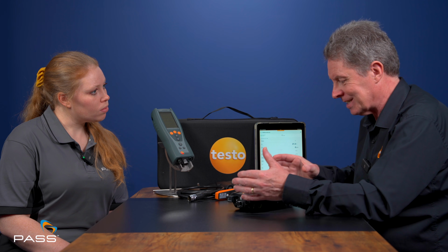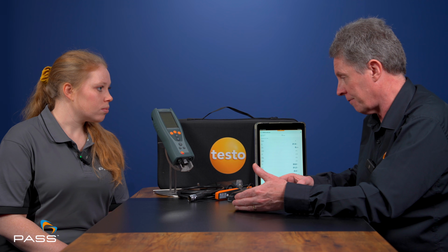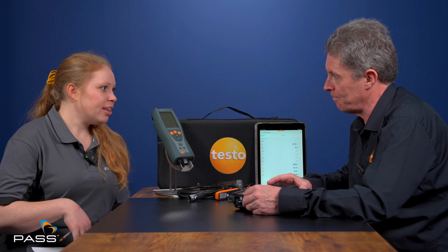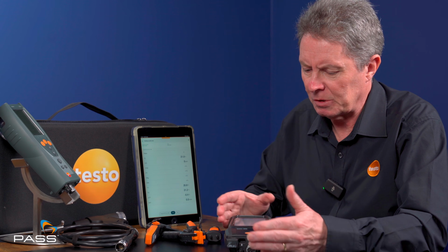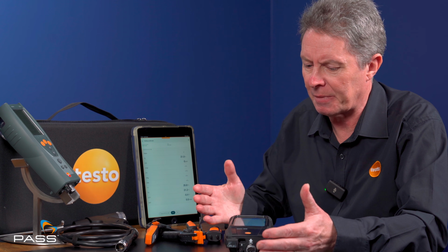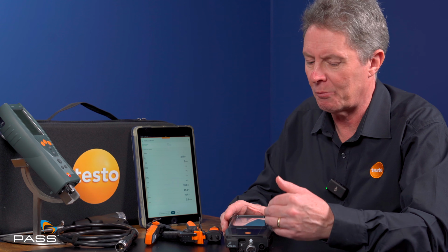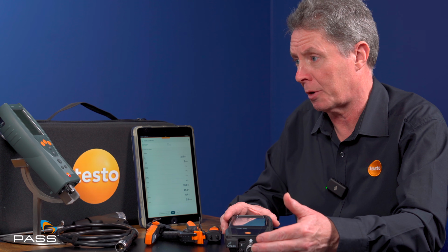If you've got a commercial burner or boiler application, then something like the 300 LL is the right design. It's maybe a slightly more expensive instrument to purchase initially compared to domestic, but your 5-year sensor life and the fact you can handle any CO spike up to 30,000 ppm means your running costs overall over many years will potentially be less. So the domestic, we're thinking of home boilers? Yes, we would class a domestic boiler as up to around 50 to 55 kilowatts. Once you start going above that, we start to think of them as commercial boilers.